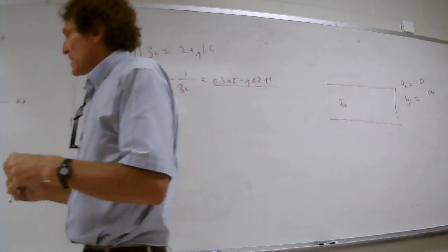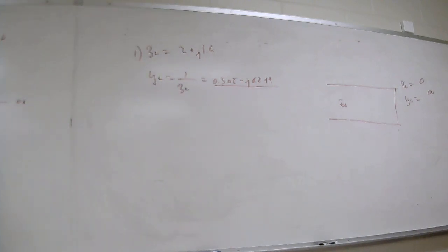Now, just watch. This will make sense. So we're going to go to this point right here. My bad. So take your straight edge, drop right through here, and give me wavelengths toward generator there. Remember, admittance. You got 0.172. 0.172 lambda, and you can look at Whitworth's solutions if you want.